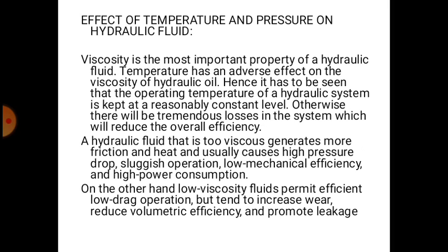A hydraulic fluid that is too viscous generates more friction and heat and usually causes high pressure drop, sluggish operation, low mechanical efficiency and high power consumption. On the other hand, low viscosity fluids permit efficient low drag operation but tend to increase wear, reduce volumetric efficiency and promote leakages. So these are the effects of temperature on the hydraulic fluid.